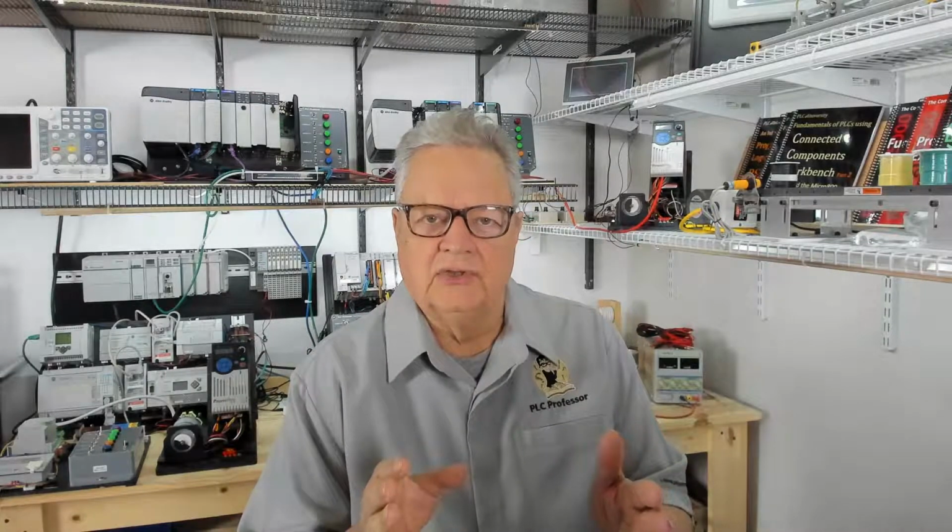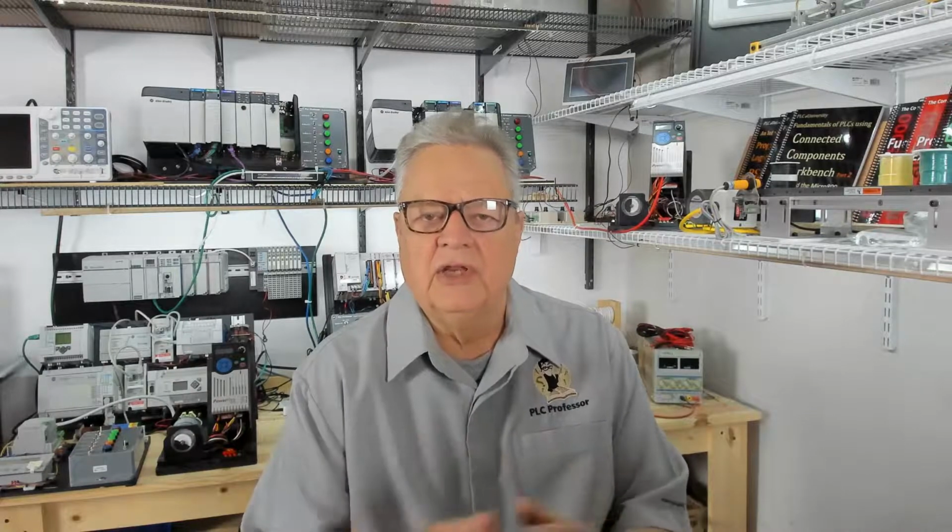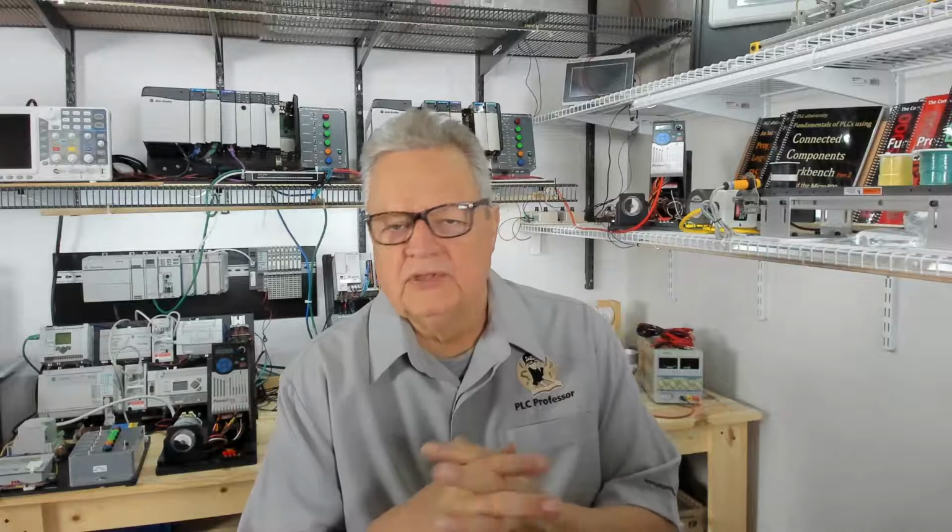And then proximity switches or sensors on each end of the stroke, which means that we would be using timers to simulate the time lapse between when you energize a solenoid and then it leaves one sensor as the piston extends, and then after a period of time it trips another sensor. So virtual devices are basically just code that in a roundabout way creates the time element of the change in inputs and outputs, similar to what a real device would do. So let's jump in here and start doing this.